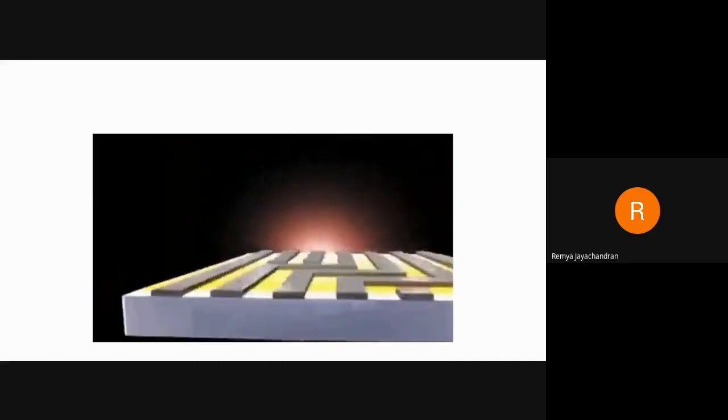First, dopant atoms are injected into the silicon structures. This is the doping process, by ion implantation. These atoms then distribute randomly in the silicon lattice. At high temperatures, in the diffusion process, the doping atoms become flexible and take on a fixed position in the atomic structure.